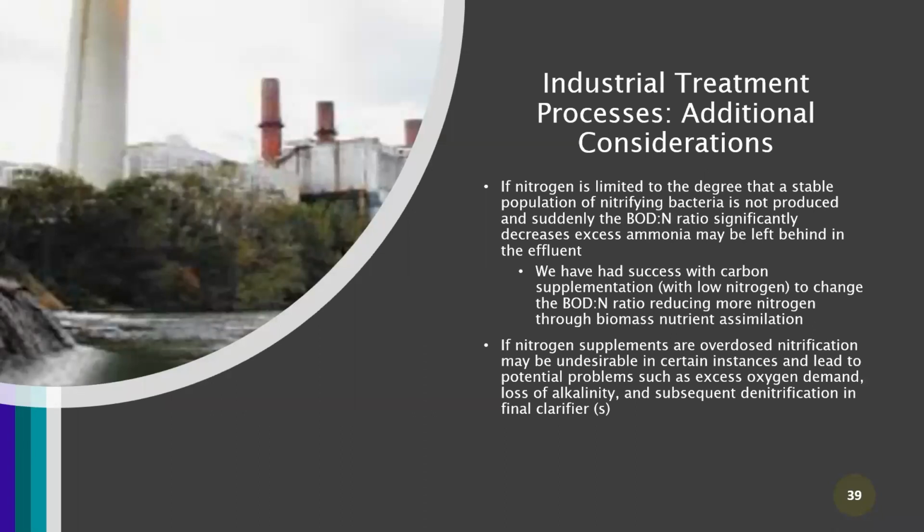So generally, you want to start with what you can change easily, kind of low hanging fruit. Then you want to look at septicity, and then if that's not the case, you're looking at, is there any sanitation chemicals or things like that being used in the process that could be damaging the nitrifying bacteria.